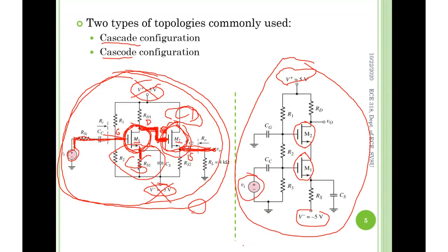By the way, what is the DC analysis for? Anyone remember? They're a DC power supply, providing the external power for the amplification. But what are we conducting or designing the DC analysis for? Anyone remember? This is about something we learned. Say that again, Kevin. It's to confirm we're in the saturation region and actually doing amplification. Great, excellent. Remember the reason.